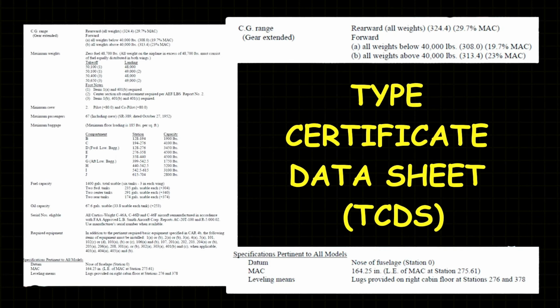Moving on to the problem solving, in this part, we will apply the concepts by organizing the given values into a table of weight, arm, and moment. To compute for the EWCG, we first list all the scale readings along with their corresponding weight and arm.